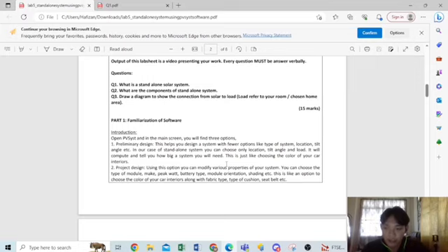Next is the battery. The energy generated by the solar panel is stored in the battery bank. The size and the capacity of the battery bank depend on the energy needed by the user. Next is the inverter. This device converts the DC electricity stored in the battery into AC electricity that can be used to power household appliances. The next is a backup generator. In case of a prolonged period of low sunlight or high energy consumption, a backup generator may be necessary to supplement the solar system's energy production.